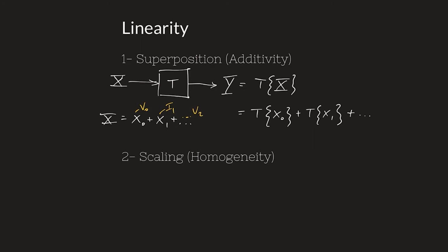Then whatever sources we have driving the circuit, if the circuit is linear in those sources, then it's just going to be the output due to each one of those individually. So in the cases that I'm giving you here, these are all actually just V. So we're going to say V0, V1, and so forth. So that's the superposition principle.